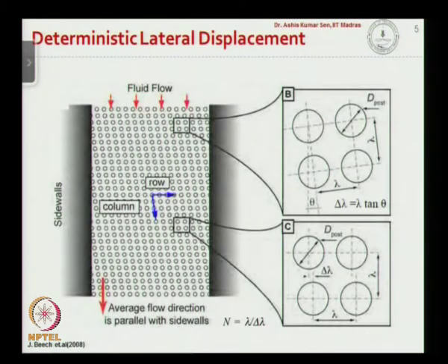Next we will look at a technique called deterministic lateral displacement or DLD. Here we have in the channel an array of posts that are sticking out from the channel, okay, and the deterministic lateral displacement is based on the principle of steric hindrance. Steric hindrance means the wall is trying to apply a force on the particle to escape from one streamline to get into another streamline, okay, that is known as steric hindrance.